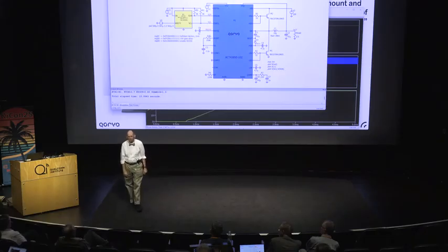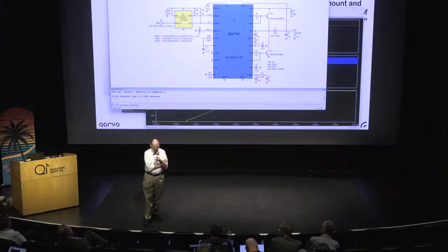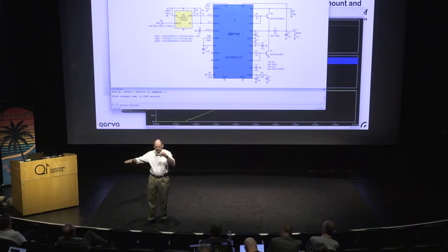So you still have, for example, this capacitor primitive in QSPICE. It has a built-in ESR. Yes, there's a built-in ESR for capacitors, and an addition there is you can say VSAT for the saturation voltage when you start losing differential. If you have a ceramic capacitor, there are 3 points you can give to have the thing saturating with charge. The initial value, and then you can pick a point, or say at this voltage you have this much reduction. So it's VSAT and SAT frac. So you can pick any point along here, and then it's the CSAT, the value asymptotically approached.